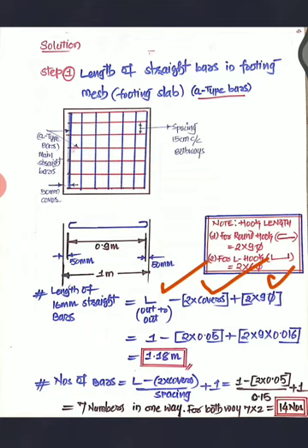So it is going to be 1 meter minus 2 times 0.05 plus 2 times 9 into 0.016. So it is going to be 1.18 meter. So straight bar length is 1.18 meter. Now you are supposed to determine the numbers, as the spacing is given.